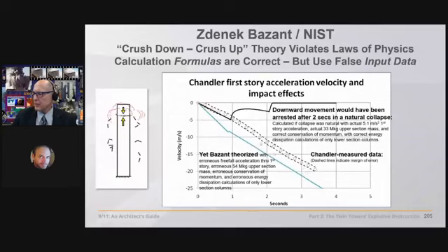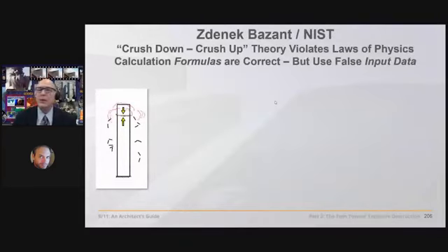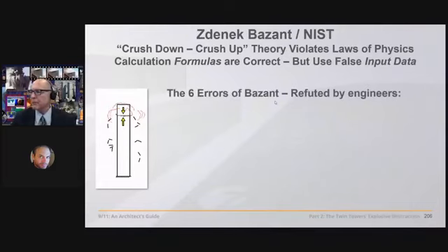Well, the slope is the same, but in reality, as that buckling would be occurring and bending stresses on those columns, there would be a resistance and a complete arresting of the downward movement, even with an impact load.